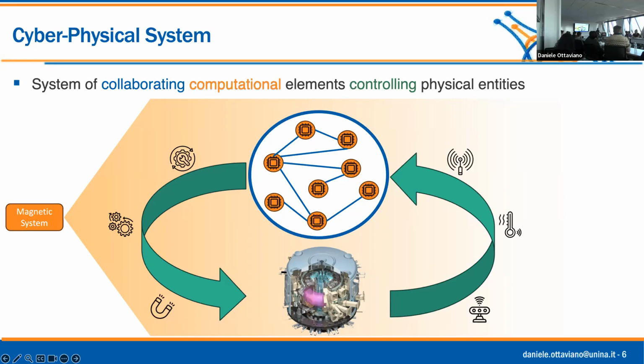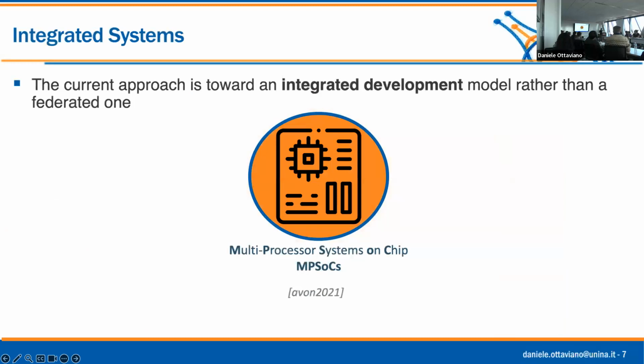Maybe they need an accelerator, an FPGA or a GPU. So they think, okay, let's replace these microcontrollers that cost a few dollars with multiprocessor systems on chip, the ones I was talking about here, that are thousand-dollar machines but are still embedded systems somehow, with accelerators on top like GPUs and FPGAs. So this kind of application, which we don't need to execute on a powerful HPC processor, we can execute on this kind of processor. That's the idea.